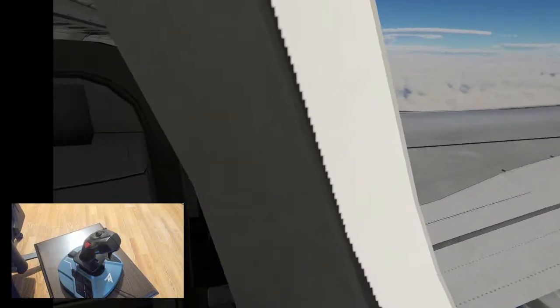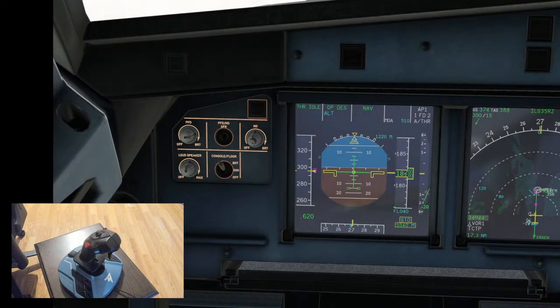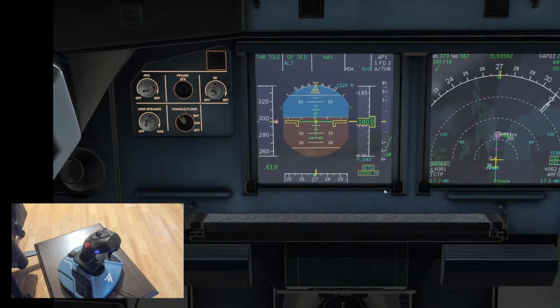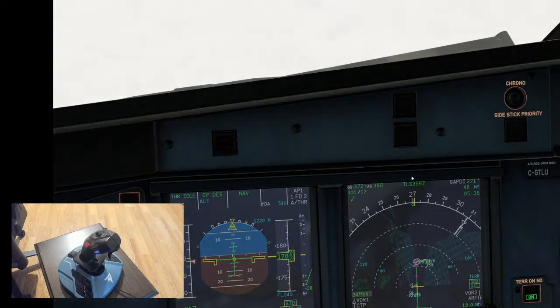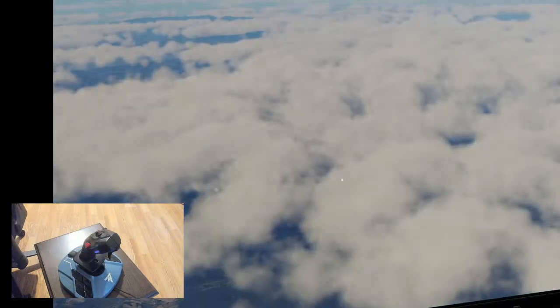At the moment again we are on the descent. Latest situation is we are passing flight level 180, 18,000 feet, and we are heading for 4,000 feet for runway 35 right Zulu. Barometer standard currently, and at 7,000 feet later I will change it to 1012.